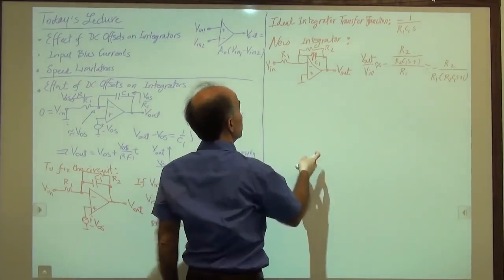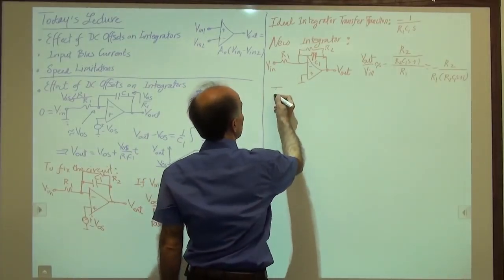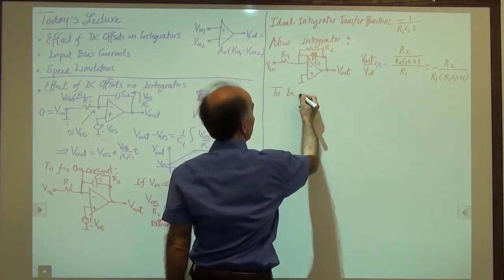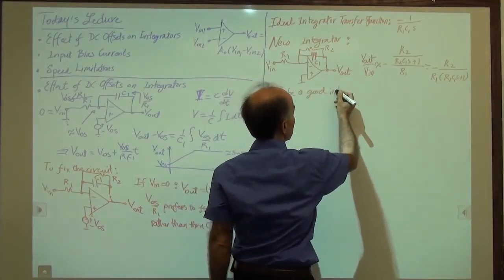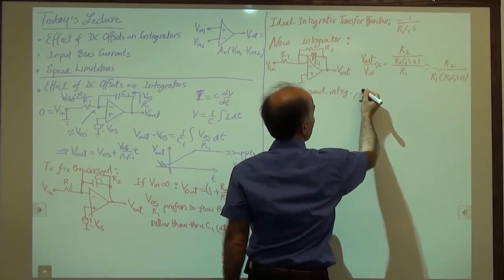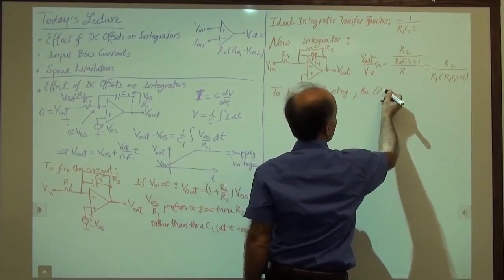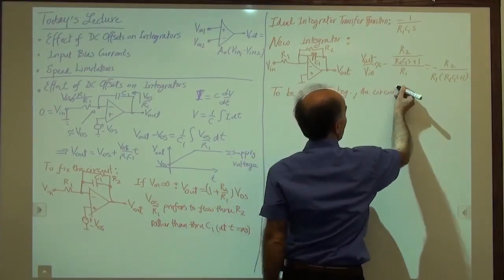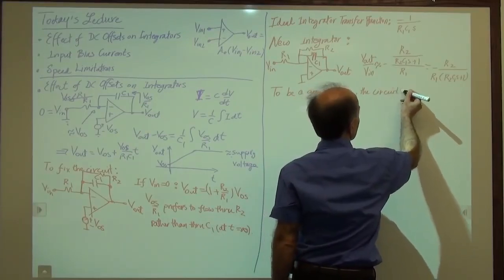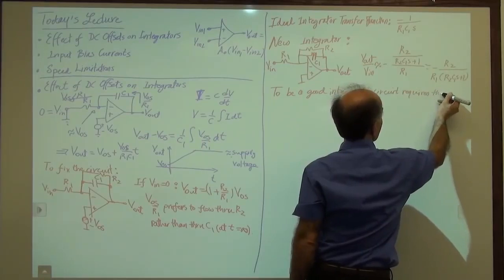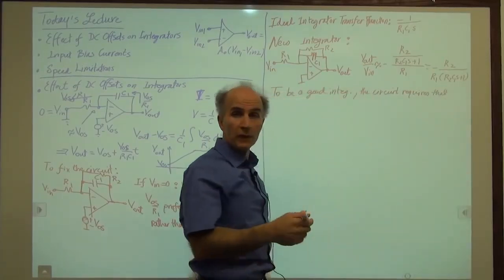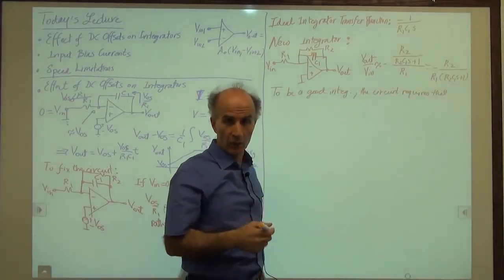So to be a good integrator, the circuit requires that R2 C1S be much greater than 1.